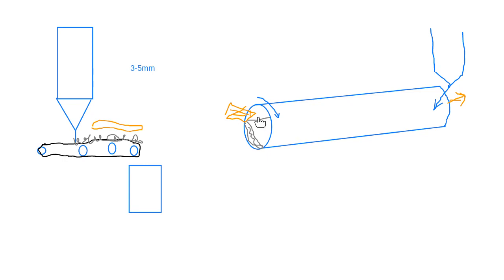The problem is if the particles stick to the sides, you get what they call banding. So you get a whole big band of stuff that sort of blocks up the rotary kiln, and that sort of band, because the particles are sticky, it will just grow and grow in size, and there's no way to easily just knock off that band. It requires maintenance, needs shutting down the plant. So it only works really well when you have a non-sticky substance, non-sticky solid. So that solid should be able to roll freely as the particles get to the top, and be able to roll freely down the surface.